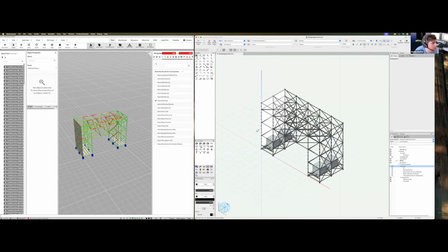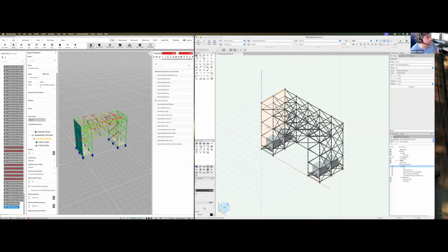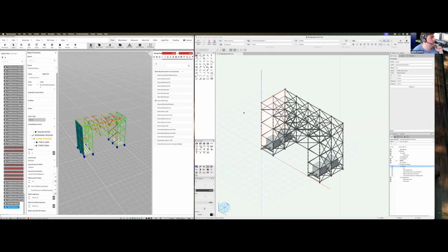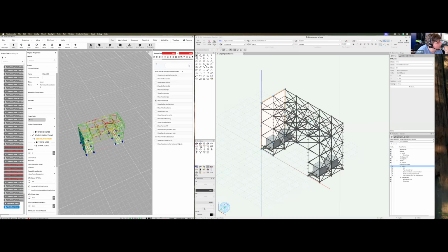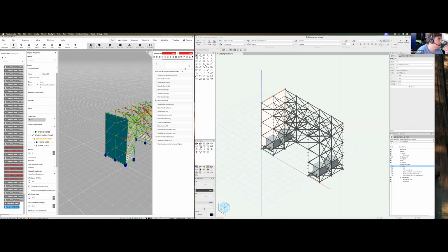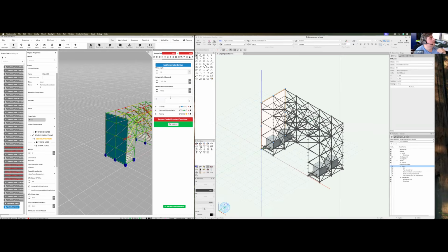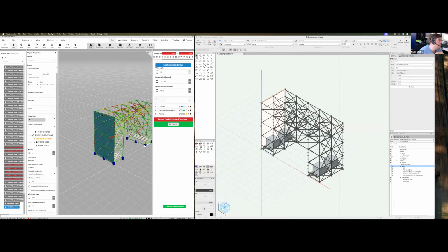Okay, so let's take this in here. So when you have wind loads, the obvious thing in here is the area. So I changed this to square foot. So the wind comes from, and you can put in the wind load direction. Here with this, the wind comes from this direction. So it's pretty obvious that the wind is blowing against this thing. It's really easy to calculate the pressure. So one could think if you have this area, this amount of pressure will actually be applied to this. But it's a little bit different.